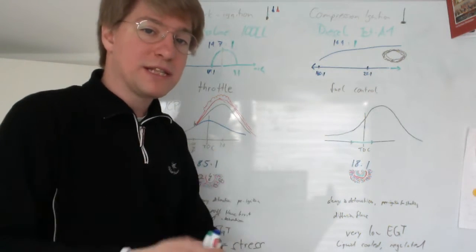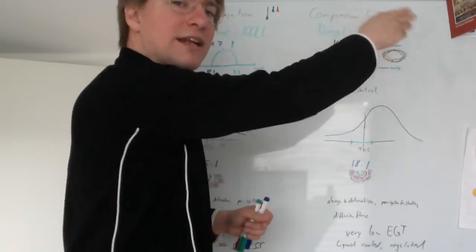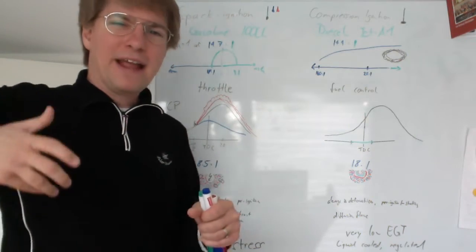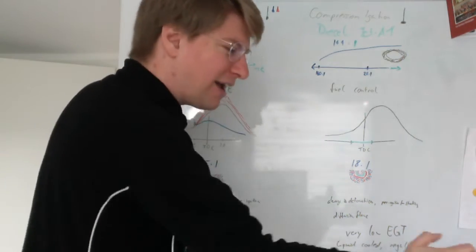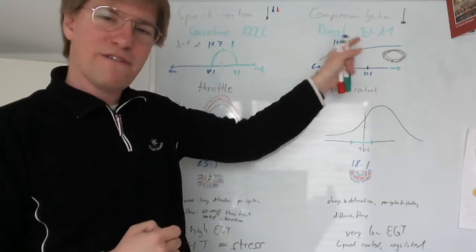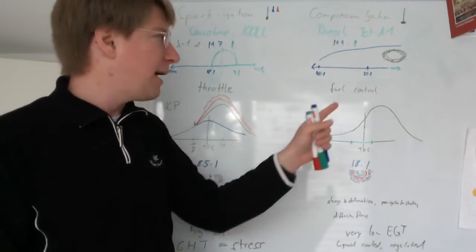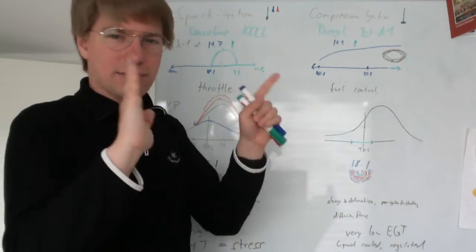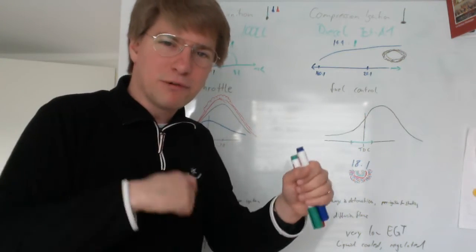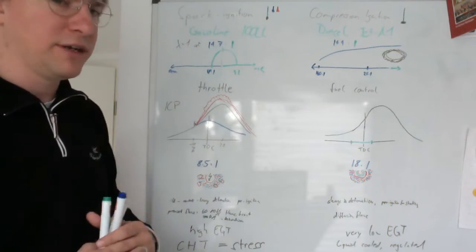Then the engine spins up, the RPM comes up, so we are sucking in more air, so we can inject even more fuel. Then the turbocharger starts to spin up and is compressing even more air into the engine, so we can jack up the fuel even more at 25 to 1. And this is how we arrive at maximum power, by keeping the fuel ratio at a maximum of about 25 to 1, and then ramping up the air input by increasing RPM and increasing turbocharger output.